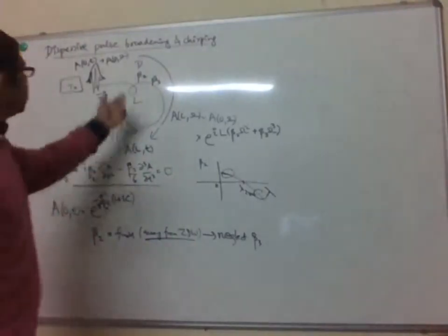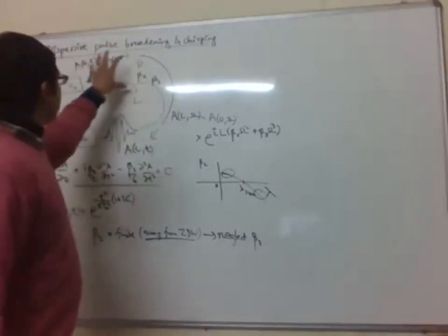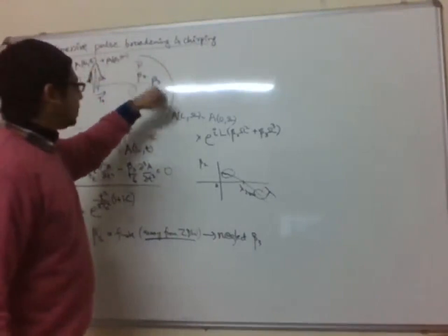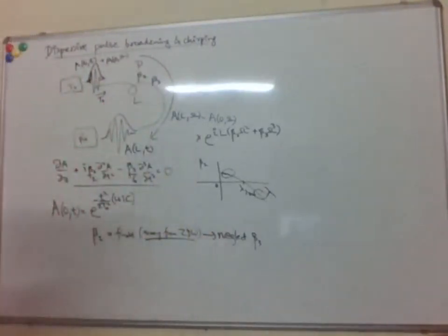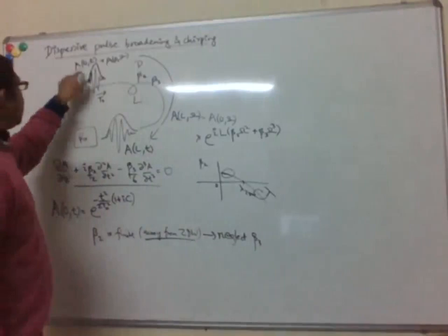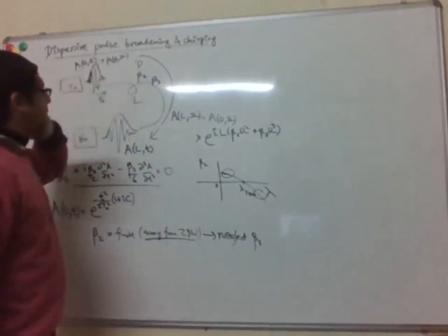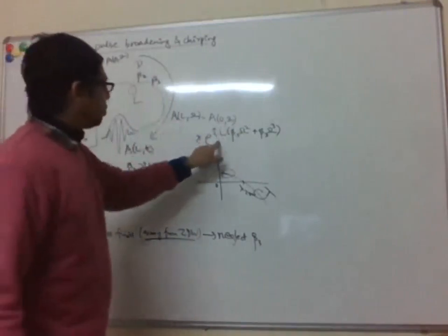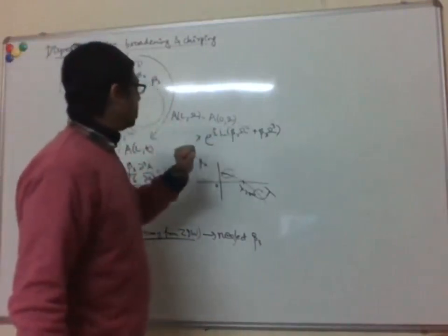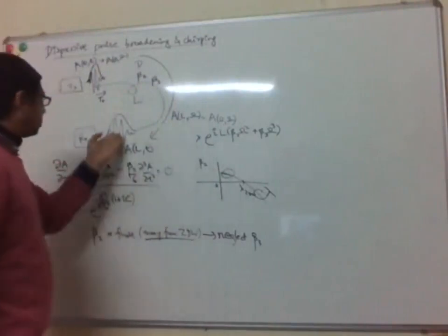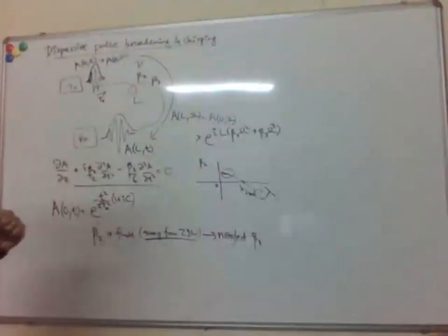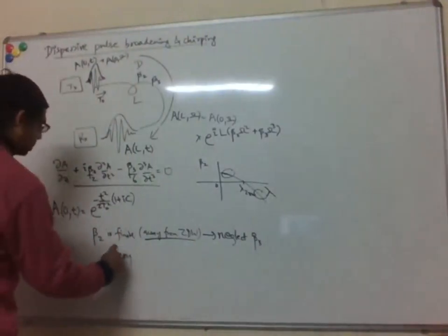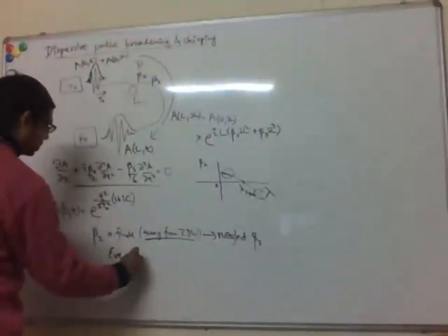Okay, and in that case, basically all of this can be analytically solved, and all the functions here remain Gaussian, right? Because you have a Gaussian function in the time domain, you take the Fourier transform, you get a Gaussian function in the frequency domain. Now you multiply by this phase. For the beta 2, it's still a Gaussian, right? When you take the inverse Fourier transform, you again get a Gaussian pulse. Okay, so in this case, everything remains Gaussian, of course, with complex coefficients.